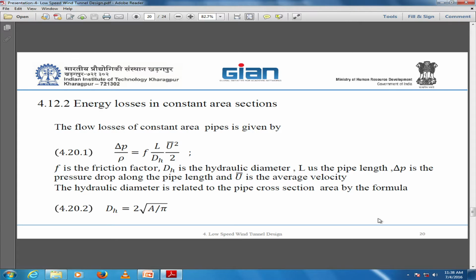And if you go further and you know that actually the friction is the cause for the pressure drop in your pipe, you equalize the force exerted by the friction, by the shear stress, to the force exerted by the pressures, the difference in pressure in two sections.